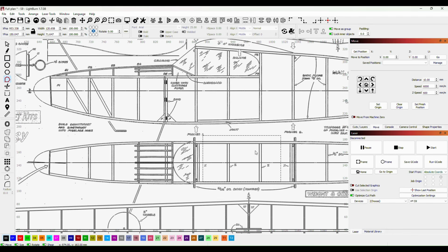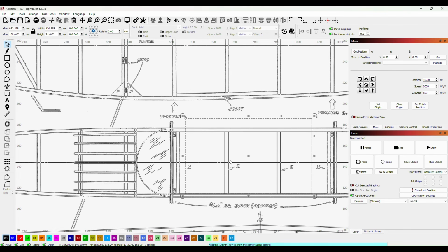So all I'm going to do is convert it back to an ordinary shape, and then I'm going to bring that down until this corner here is right on the edge of the longer run again. So I'll just press Control and Shift, and then using the down arrow I bring that edge down until it just touches or lines up with that top edge there.